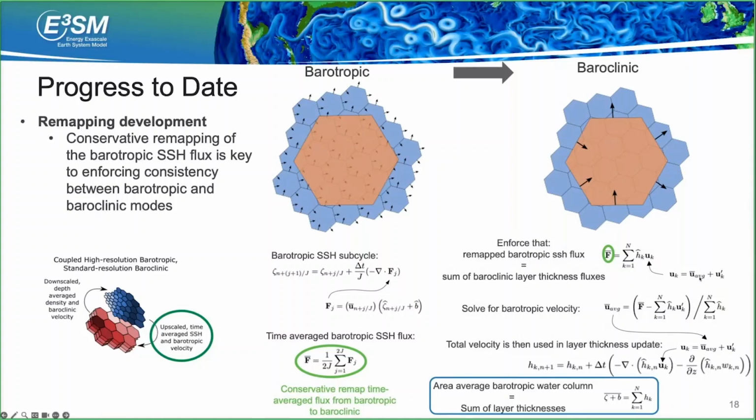And so this total velocity here can be split into the barotropic and baroclinic components, and that allows us to solve for the depth average velocity that satisfies this condition, so that when we update the layer thicknesses in the baroclinic mode, we hopefully preserve the property that the area average of the sea surface heights within this baroclinic cell on the barotropic mesh is equal to the sum of the layer thicknesses. That will allow us to make these modes consistent despite having them on two separate resolutions.